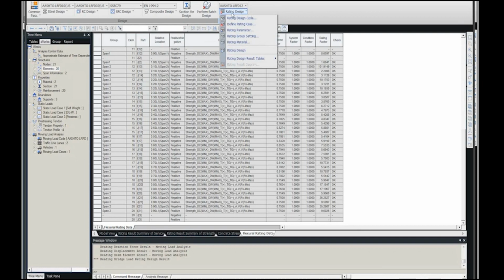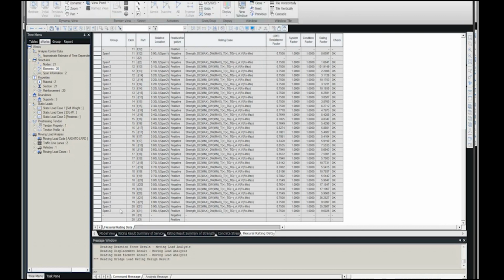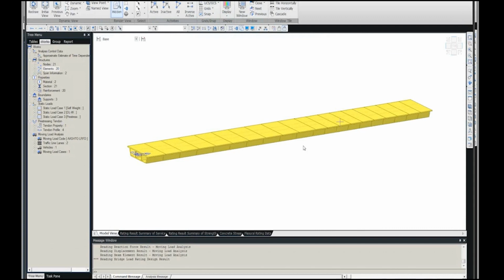You see that using MIDAS Civil for load rating makes it so easy. Now you created your model, you can perform any type of analysis that you want on top of the bridge. Let's say you have moving load, you have construction stages, you have seismic loads. You can perform all those loads, get the results, bending moments, shear forces, deflection, anything that you need for your design. You can simply run the design, or run the critical section, or select a certain section and run the design.